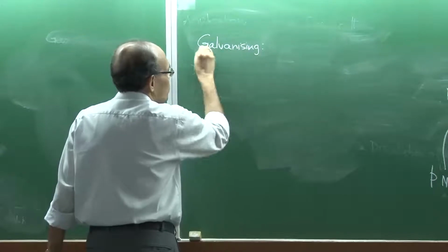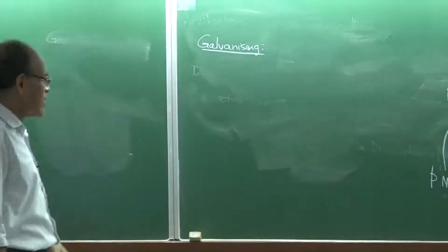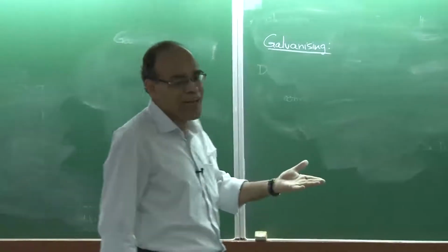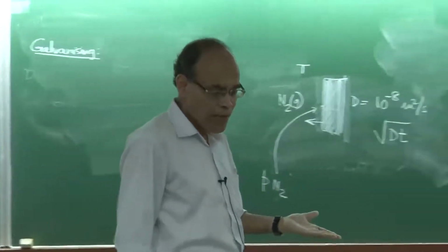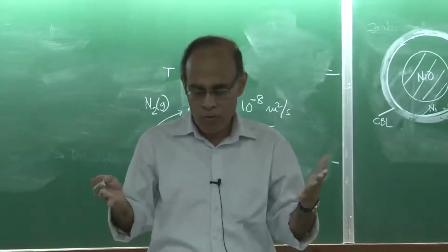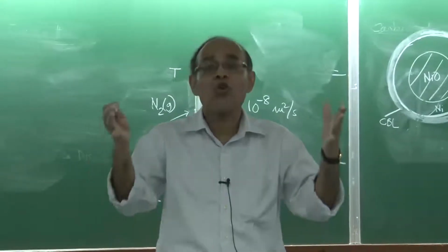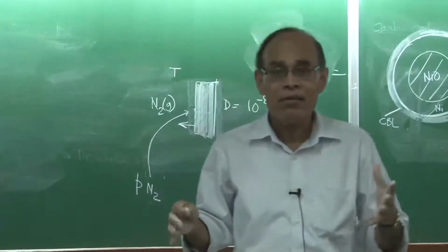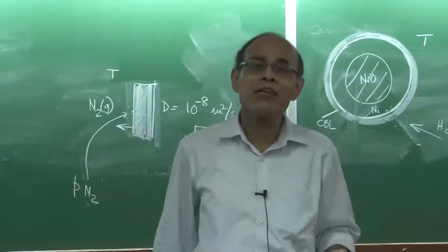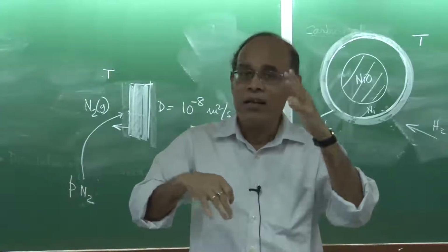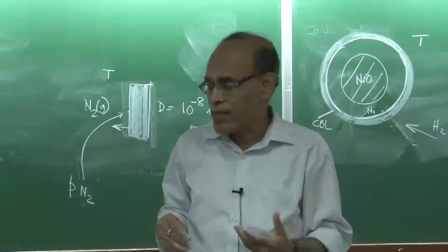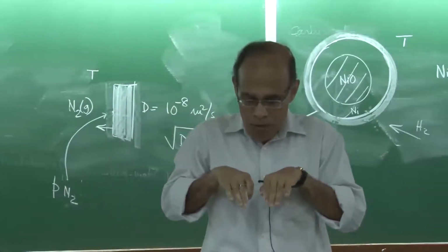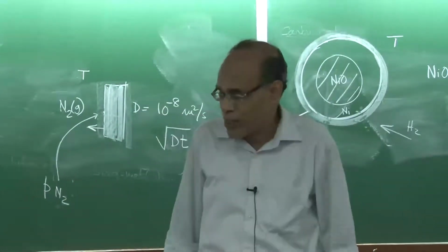I am not going to write the exact process, I am only going to explain it to you. Galvanizing, the hot dip galvanizing process, for example, you may be knowing. Okay? You produce hot rolled coils, for example. Those coils you may have seen when you are traveling, a big truck carrying about 12-ton, 15-ton single coils, and those hot rolled coils basically are moved through a zinc bath with a certain speed.